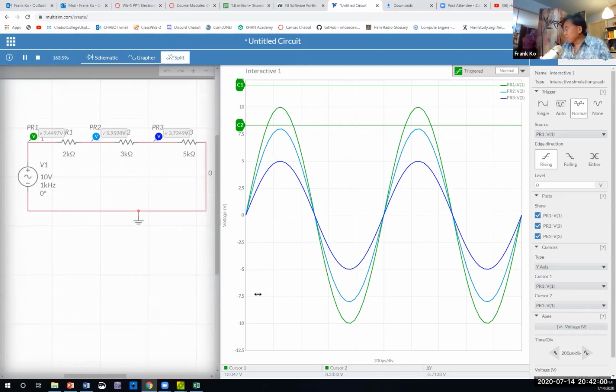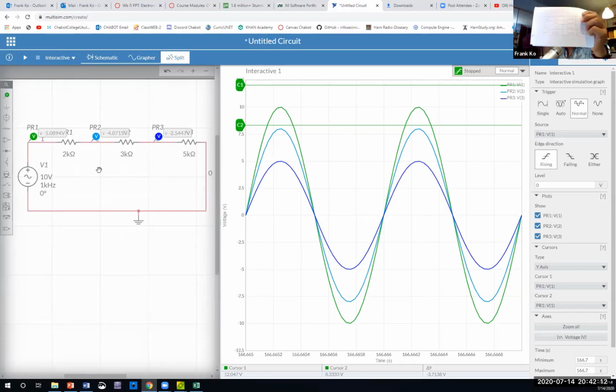So we went through this exercise together, the exercise of this circuit. We did a VIR analysis of this circuit. We filled in the VIR table for this particular circuit. We had predictions for voltages across each of these. We put in test points, and from each of these test points, we have an expectation of how much voltage to ground, and we were able to display a waveform that confirms those voltages to ground.